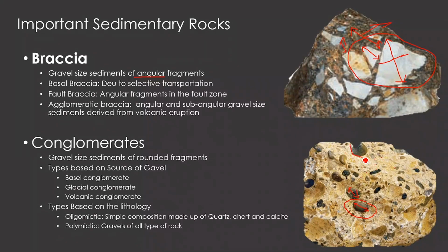So this rock we call a conglomerate only because, in some aspects, both are the same: the size of the main grains is the same, and the cementing material may be the same. But the primary parameter which differentiates between these two kinds of rocks is the shape of the grains. In breccia, the grains are angular in shape, whereas in conglomerate, the sediments are rounded in nature. When you say this is the classification, there are so many stories associated with the difference in shape.